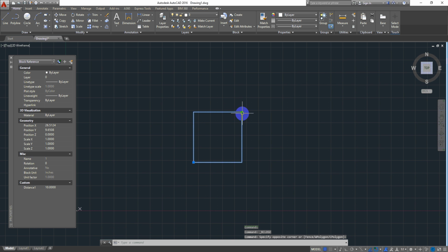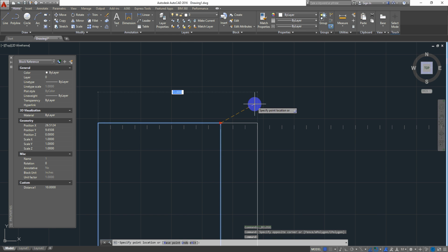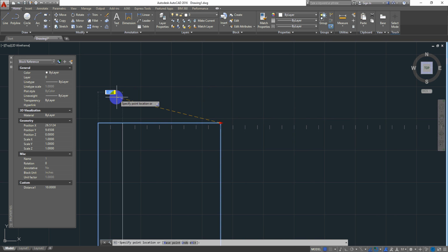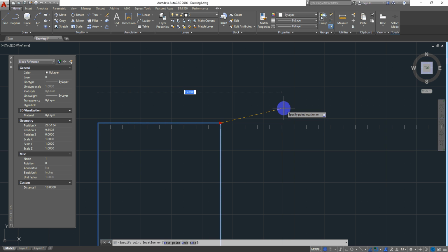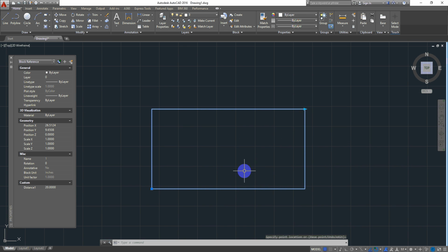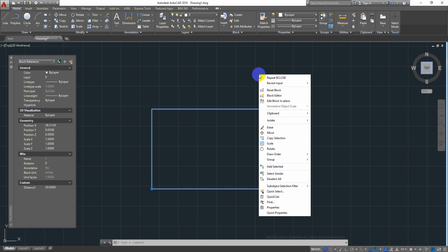Now you can see I will be able to stretch this rectangle, this square, every 1 unit only. That is, this is an incremented value. So based on the value I provide for that increment distance type, I will be able to stretch this rectangle using the linear parameter.